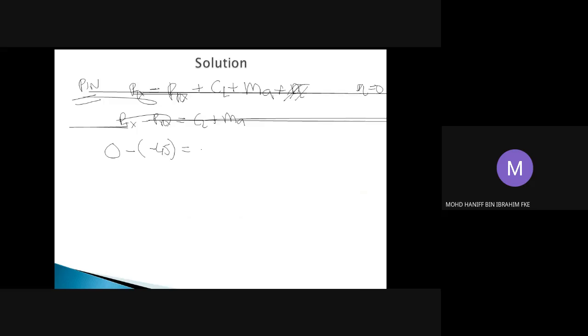For the channel loss, we have 4 dB per kilometer, the attenuation of your fiber, multiplied by the length, which is planned to be 5 kilometers of fiber optic cable, given in the question. For the connector loss, we have 11 connectors multiplied by a loss of 2 dB per connector.